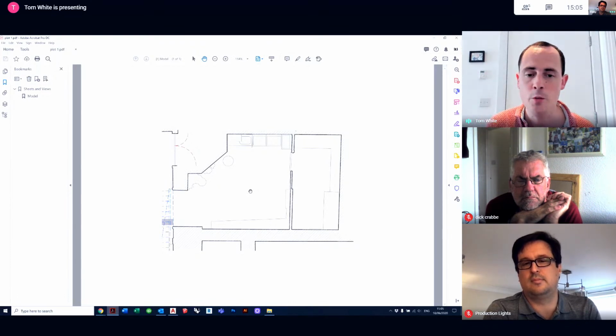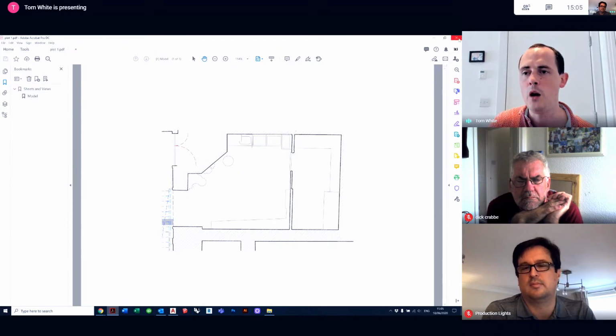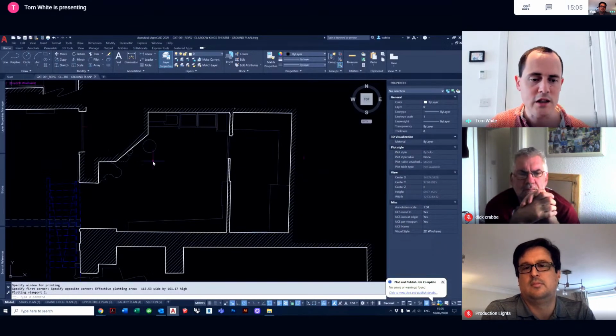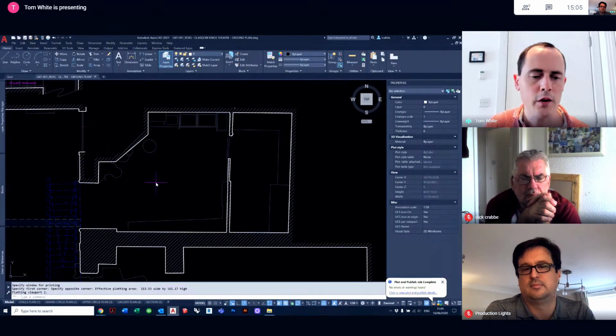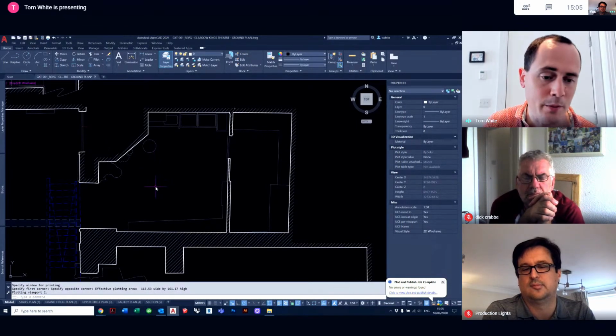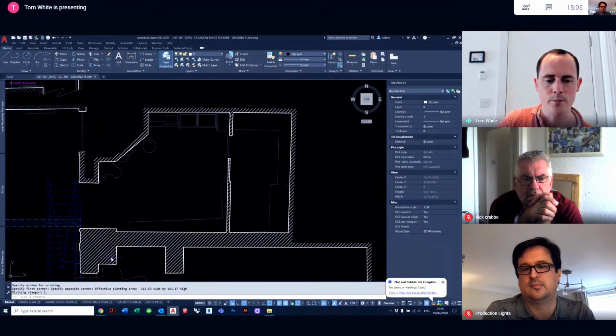And you can see it's absolutely perfect. It's a normal page, but what I can't do is replicate that process a second time. So in 3 or 4 days' time, when he comes back to me with comments, like the sink is in the wrong place or the entrance is actually going to have a double door, I'm not able to replicate this drawing exactly. So that's where I would choose to print it in paper space, rather than model space, sorry, paper space.